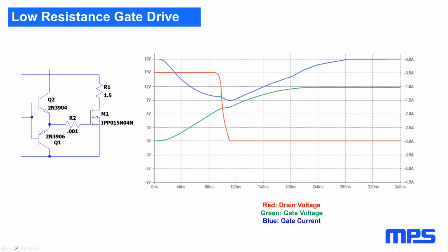So if I use this circuit with no added series gate resistance, there's a simulation of turning on the MOSFET. The gate current is limited only by the current gain of the bipolar driver. That's pretty typical of gate driver ICs, where the peak current's limited by internal devices. That peak current's generally shown somewhere on the gate driver data sheet.